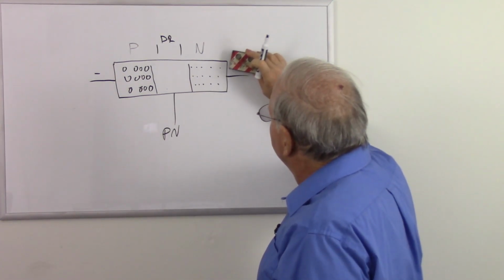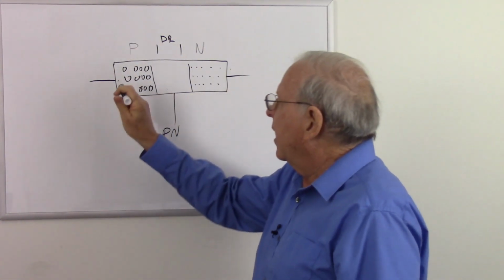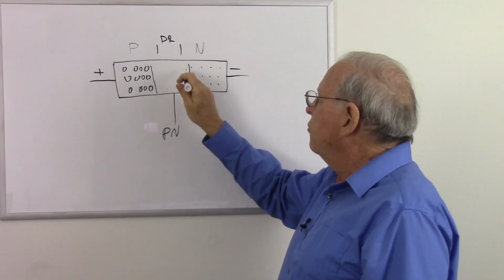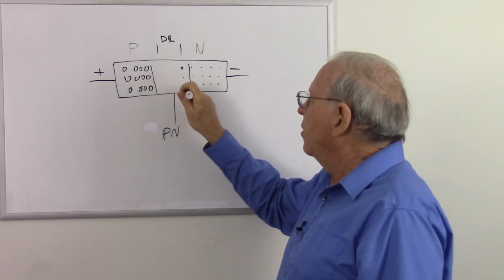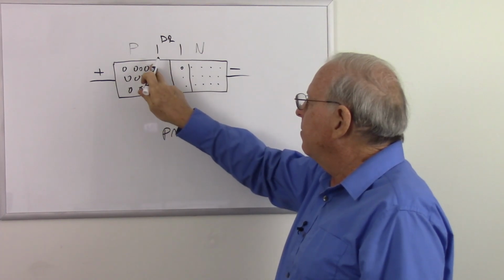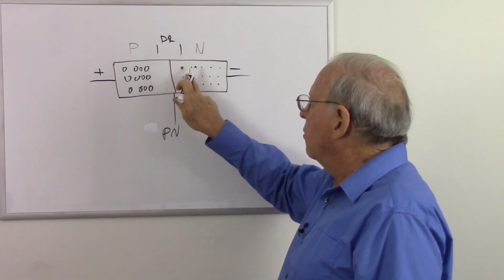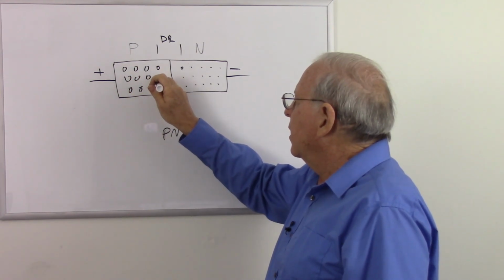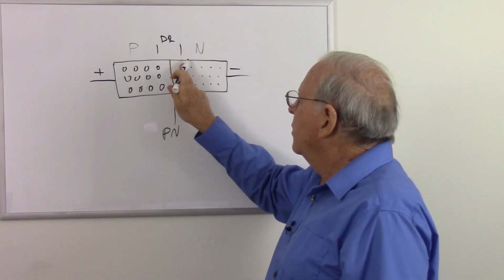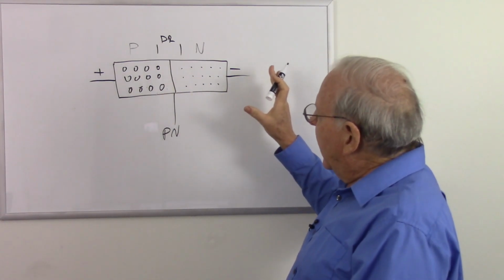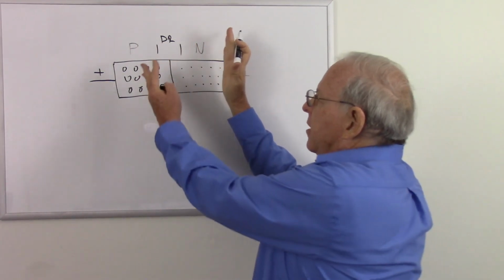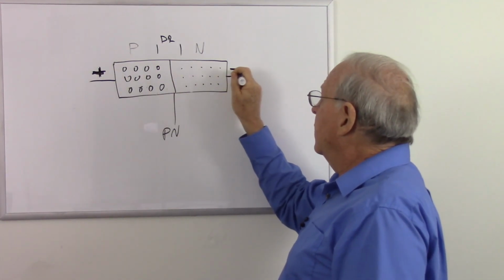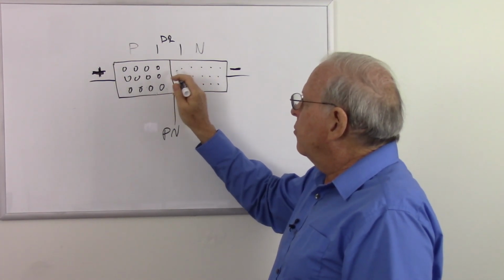So we're going to move our charges so we have positive on the P side, negative on the N side. What that's going to do is drive these charge carriers toward the PN junction. I'll draw that right back in there. Let's get rid of these lines. The depletion region is now smaller. Let's move everything closer to the junction. And it's still not conducting because we haven't completely closed that depletion region. So if we increase the voltage, that will push these closer together.